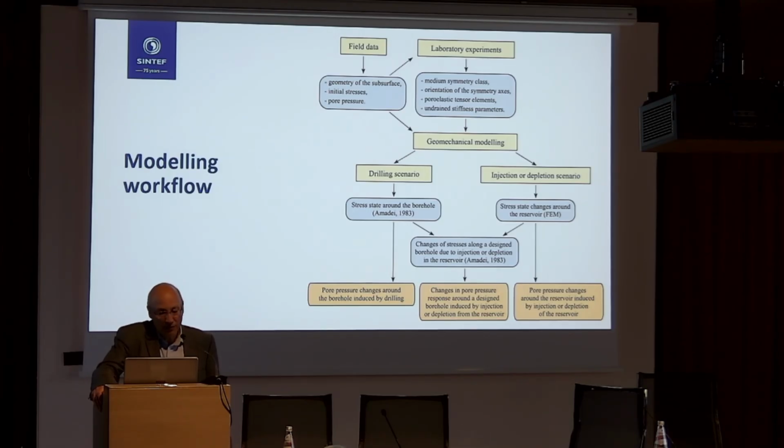You do some clever laboratory experiments, which are very time consuming because just getting a whole, non-breaking shale specimen, if it's a field specimen, is quite difficult. And you try to do all these orientations and look at how the pore pressure and the stresses change, doing different stress paths that we will come to.